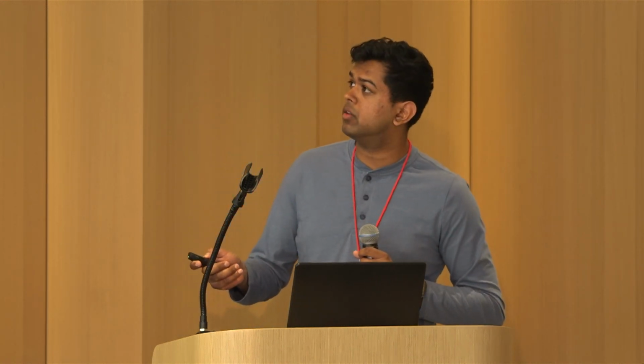So that's for MoS2. We have also started recently the growth of WSe2, which can be used as a p-type material. We're in the earlier stages of this work, and instead of an 8-inch furnace, we're starting off with a 1-inch furnace. The idea is by optimizing the parameters on a smaller scale, we can learn some valuable lessons before translating it to a wafer scale.